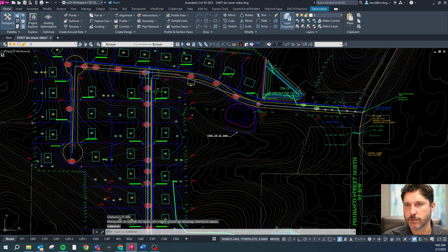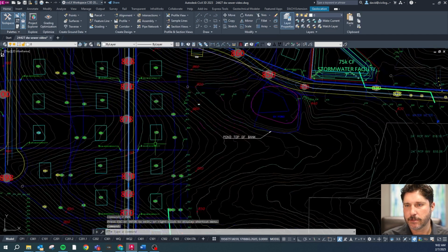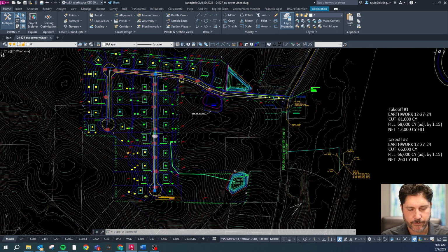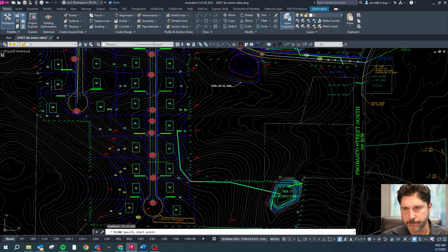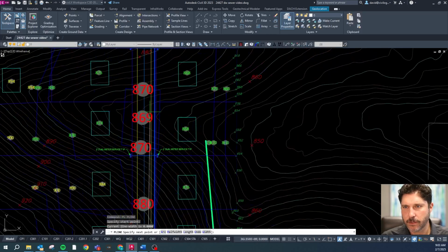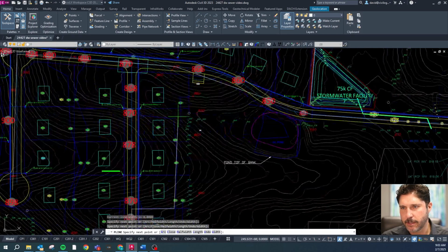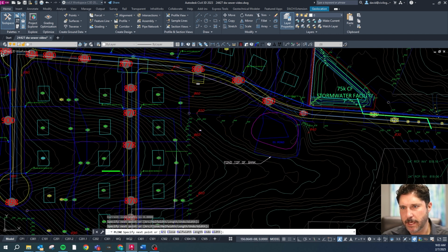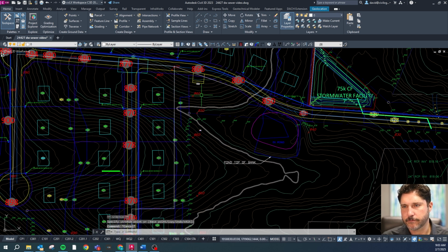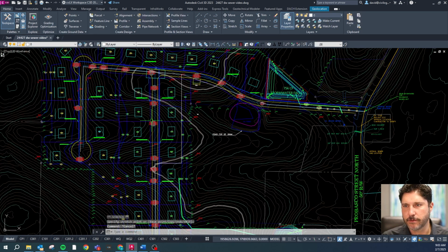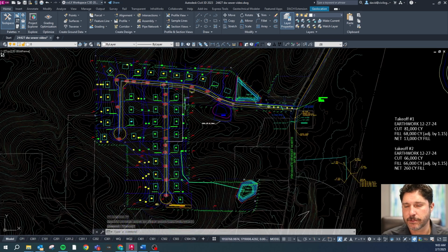So one solution that we could do is these pads, these houses are going to sit a little bit lower, and we have a 70 there. I'm just going to take that, we'll go down to this low point here, straddle that property line, go down to the 70, and then we'll just run across the back of these lots and just connect back like that. And that'll keep our trench depth less.